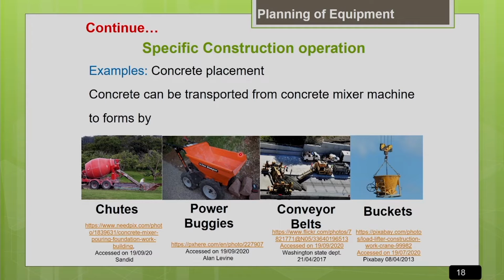Concrete pumping is commonly adopted for placement. Or I can go for a conveyor belt like this, if the rate of placement needed is very high. Or I can go for even a crane with buckets. Okay, if the concrete is to be placed at greater heights, then I have to go for a crane with concrete buckets. Okay, we can even go for a helicopter with a concrete bucket, depending upon your job site condition. If the job site is not accessible by other machines, then you have to go for the option of even a helicopter carrying a concrete bucket.